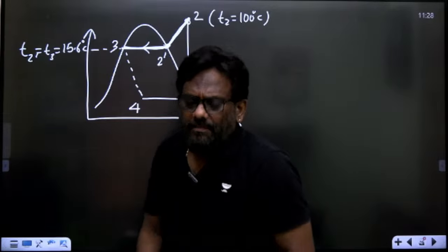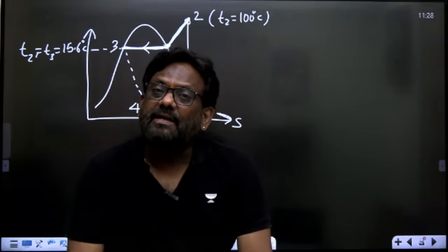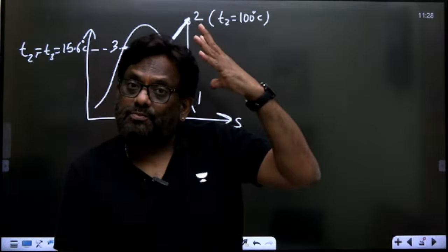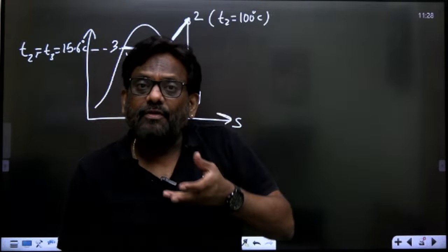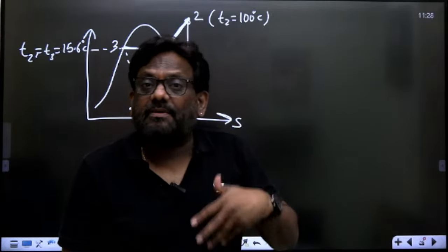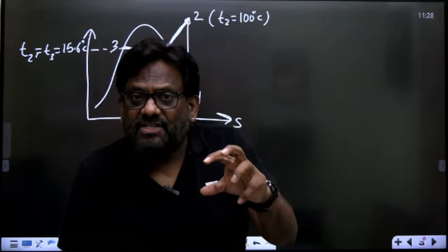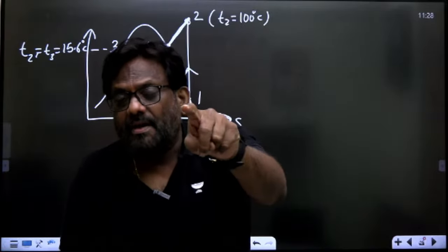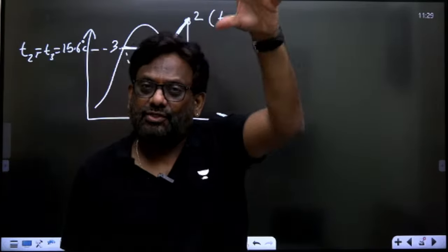Look, in a power plant, when you study the thermal power plant Rankine cycle, the boiler pressures there are very high, sir. You know, we pump it to very very high pressures, sometimes 180 bar, sometimes 200 bar, sometimes 220 bar. So at high pressures, even though the fluid is in superheated state, gaseous state, superheated state means vapor in gaseous state, but I cannot use that vapor as ideal gas because the pressure is so high.